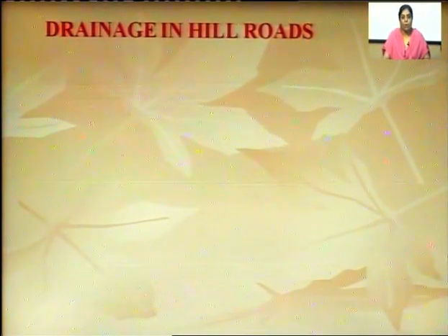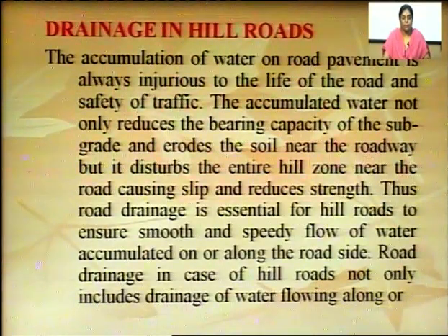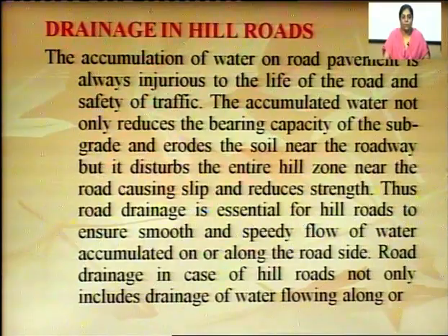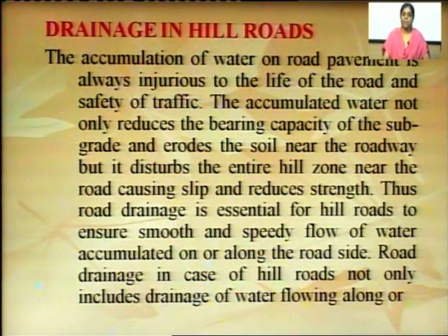So, now we talk about drainage in hill roads. The accumulation of water on road pavement is always injurious to the life of the road and safety of traffic. The accumulated water not only reduces the bearing capacity of the subgrade and erodes the soil near the roadway, but it disturbs the entire hill zone near the road, causing slip and reducing strength.